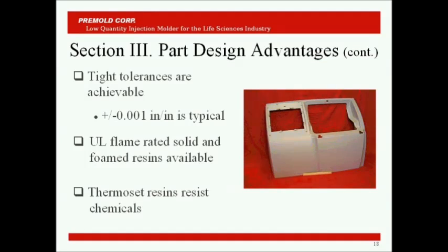You can get tight dimensional tolerances with the RIM process, fairly easy to achieve because you're dealing with a closed mold that controls all the features of a part. Unlike the process for thermoplastics, RIM does not melt a solid and then overstress it into a mold and let it freeze in that stressed condition.